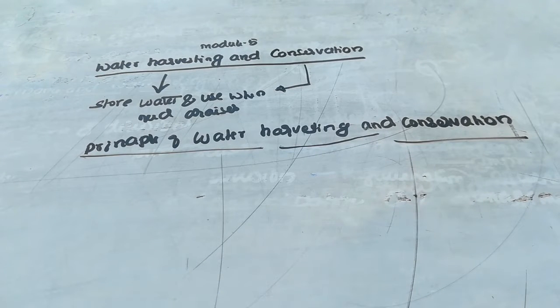First is designing which techniques to use to make more efficient use of available water. It is important to consider how crops receive or lose water. Crops receive water through rainfall, irrigation and stored soil water. They lose it through runoff, evaporation and drainage. Some key principles of effective water management follow.